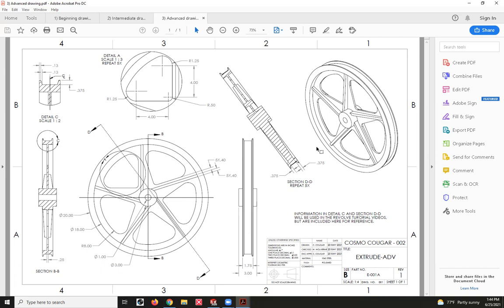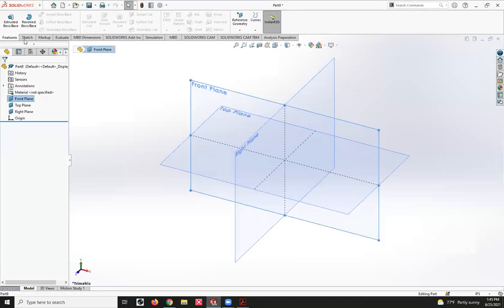Another thing I can note is the fact that this wheel is created with this big rim and this hub here in the middle, which are both relatively simple, as well as it seems everything else is built around those. So I'm going to begin by creating those two parts of the wheel, which are again going to be this hub and this rim. And I will do that in SOLIDWORKS by sketching a couple sets of circles.